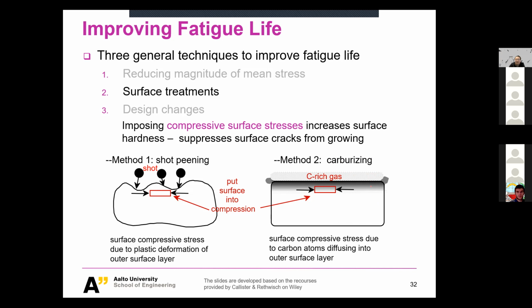And due to this, the carbon atoms are going to stay at a certain place, interstitially or substitutionally, in your material. That kind of crowded situation will also create compressive stresses on the surface. We'll talk about this in probably 2 weeks or so, because this is one of the processes to do. And the key is to prevent fatigue cracks and improve fatigue life.